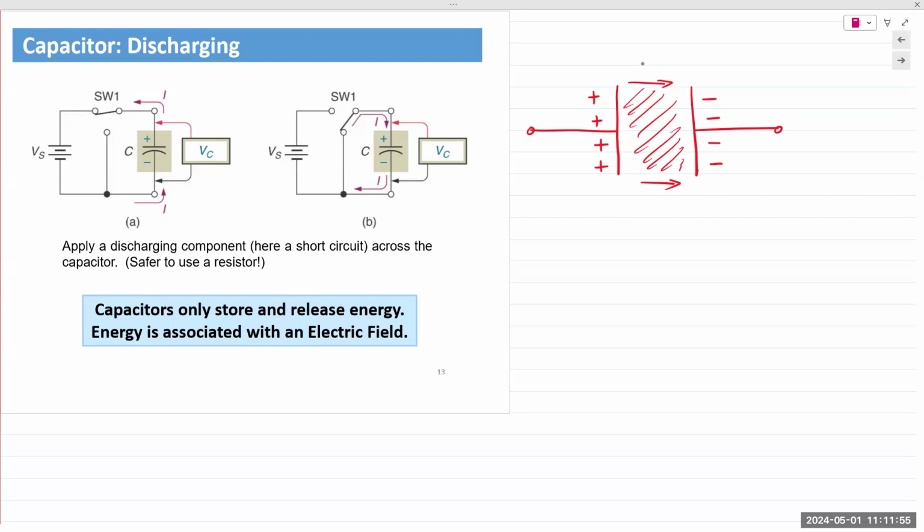Okay, and we can electrically model this as a resistor in parallel with that capacitor. So the stored energy of the capacitor would discharge through those terminals. Similar to an inductor, where we model the inductor as a resistor in series, we model the capacitor with a resistor in parallel. That allows us to explain how and why a capacitor would discharge through itself, even though it's not connected to anything. Now, of course, the amount of time it takes for the discharge will depend on the size of the capacitor. It will also depend on the amount of voltage or energy that is stored in the capacitor.